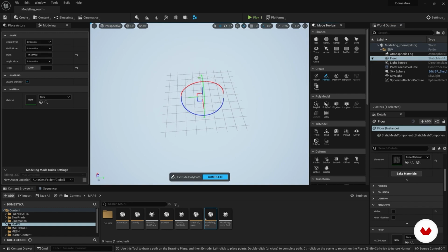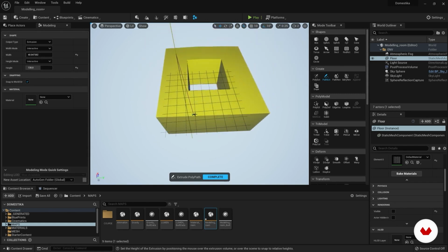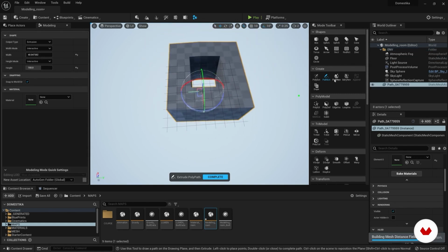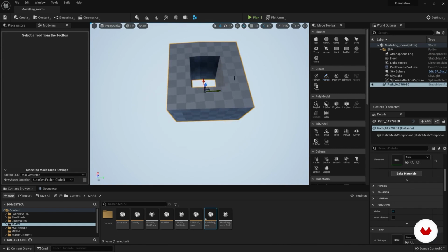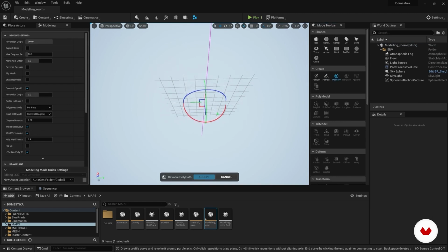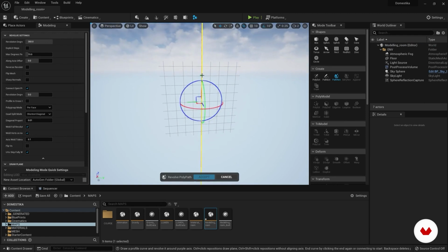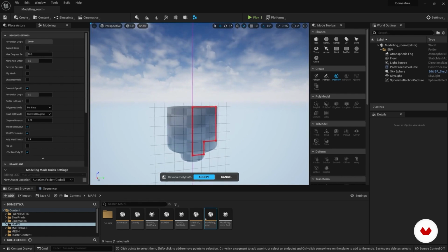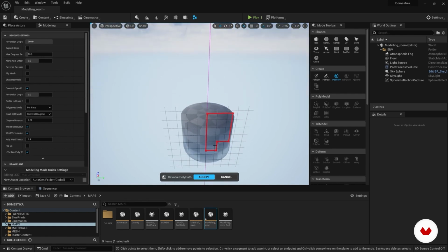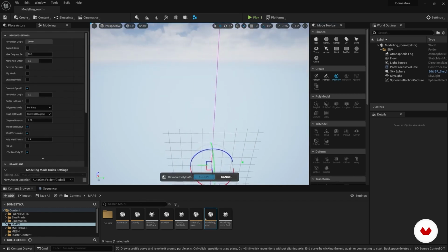Path extrude, on the other hand, is more or less the same tool, but it does this. As soon as I close this spline, it gives me the ability to create thickness and extrude it along an axis. This gives me the ability to create more complex shapes. Path revolve is very interesting. It is always based on splines and allows us to extrude with one revolution. Drawing half the spline and leaving the first 2 points at 0, what it will do is just what the name says. We'll extrude in one revolution along an axis. Let's try another form.